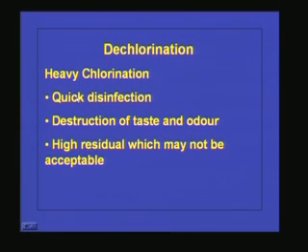Dechlorination is practiced when we need quick disinfection, when the water is highly contaminated. We know that the water has a lot of pathogens present in it. At that time, we have to add a heavy dose of disinfectant so that all the pathogens get killed very fast. Then afterwards we take the water for all the treatments, but after all the treatments, if you taste the water, it will have a lot of the disinfectant taste. So it will not be acceptable to the public. This high residual is not advisable to send into the distribution system. So if a high residual is present, then we have to go for dechlorination.